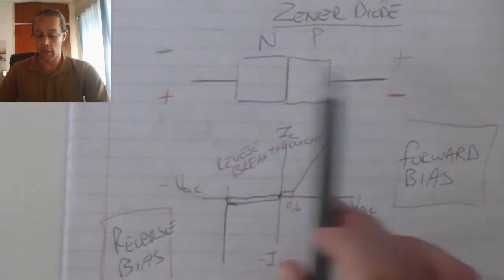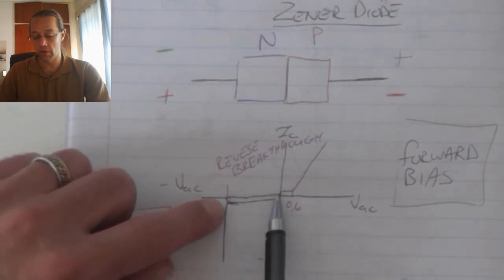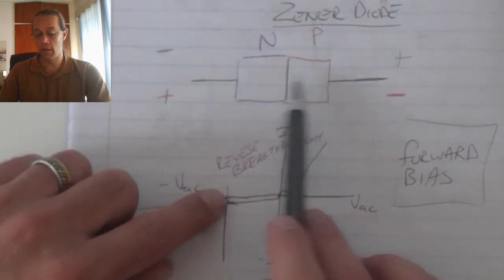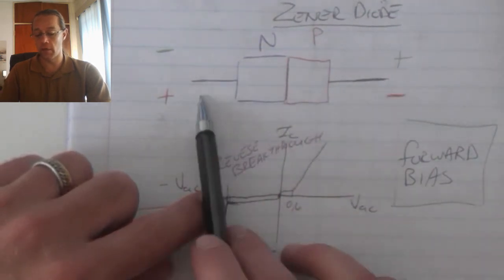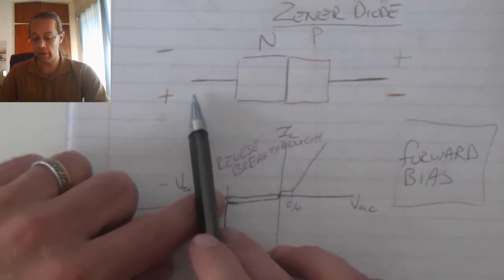So if I increase the reverse polarity up to, let's say, 5 volts, so I'm increasing that voltage in reverse direction, and when it reaches 5 volts, conduction takes place, or the depletion region takes over the entire component and conduction takes place.